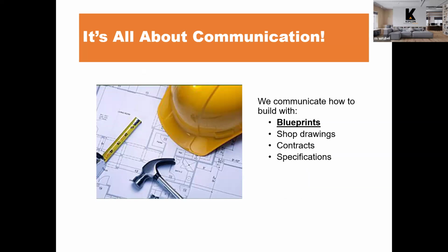So what do we need the blueprints for? Blueprints are, among other documents in a bid package, a means of communicating information on how to construct something that's either new or to repair or remediate something that is already in existence. The whole bid package includes not only the blueprints, but shop drawings, which are specialty drawings for specialty items, such as a metal stair railing that's shown on the blueprints. Shop drawings will show how to construct those stairs, the types of welds, the types of bolts involved. They're a specialty drawing from a specialty designer.